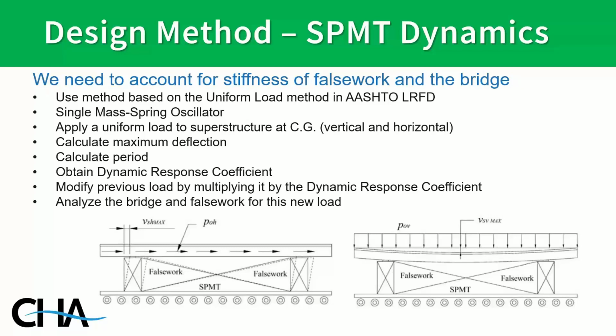We apply uniform load to the bridge, calculate a deflection, calculate a period, obtain a response coefficient, and then modify the loads based on that response coefficient. And we look at it both in the horizontal direction and the vertical direction. Very simple. One thing we also included in the guideline, though, is if you noticed before, the response spectra for